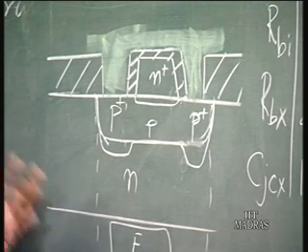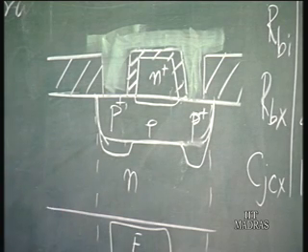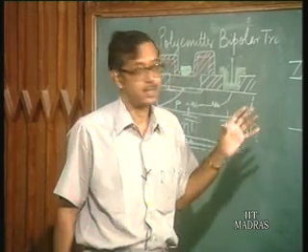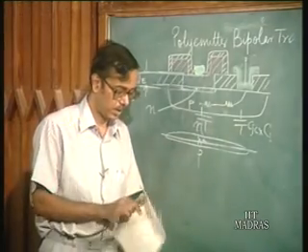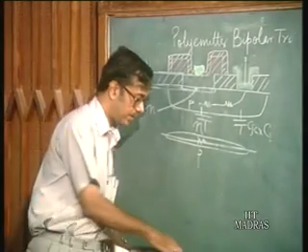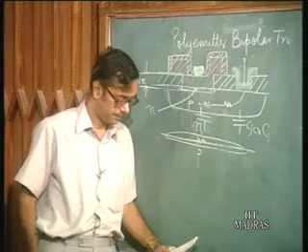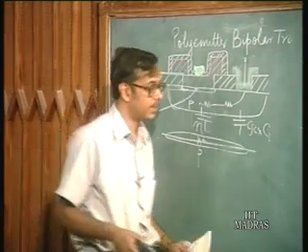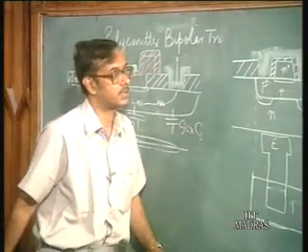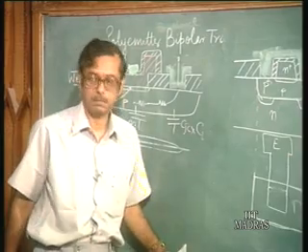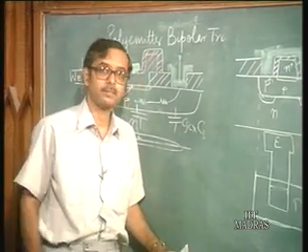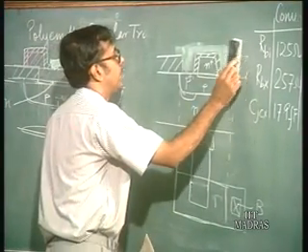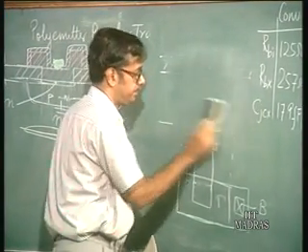And so a high speed transistor must have a self-aligned structure, so that the extrinsic regions are reduced, so extrinsic capacitances are reduced, which gives rise to lower delays. So in fact, a self-aligned transistor is going to be much faster compared to a conventional transistor. All right. Now I shall just take up one more issue here.